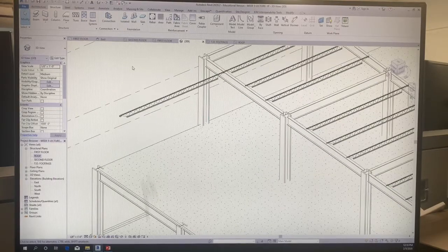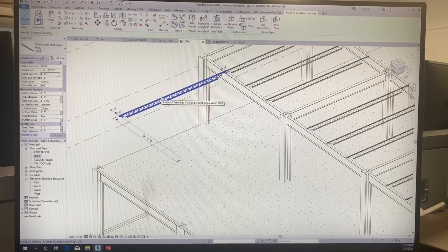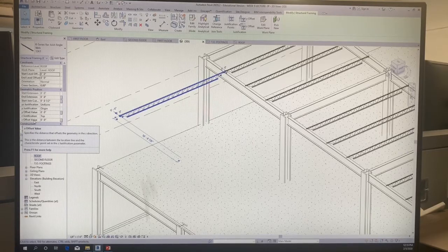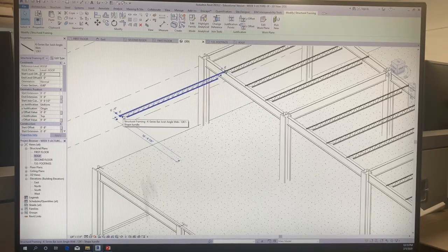So you can see again, it's horizontal right now. Okay, so earlier I taught you how to drop a beam down. Okay, but go ahead and select that beam. The way we dropped that beam down was utilizing the Z offset value. Okay, that makes the whole beam come down. Okay, all I want is this end here to drop. So here's how you make one side drop only.